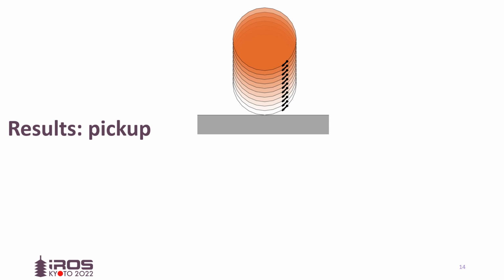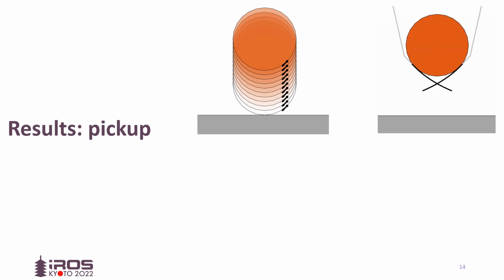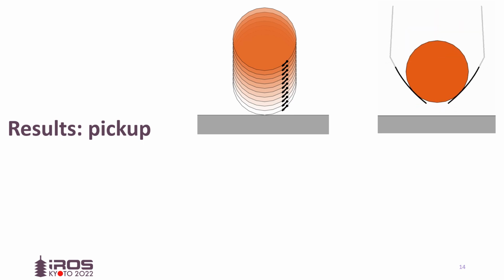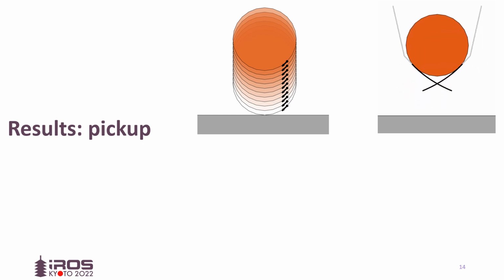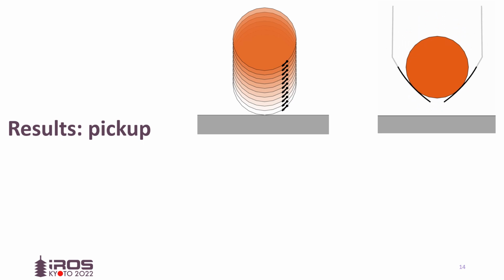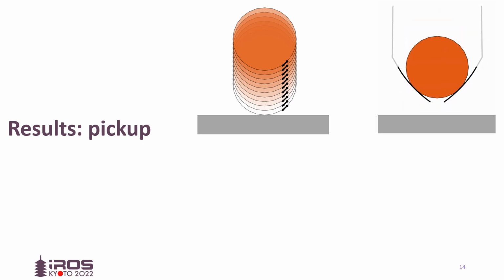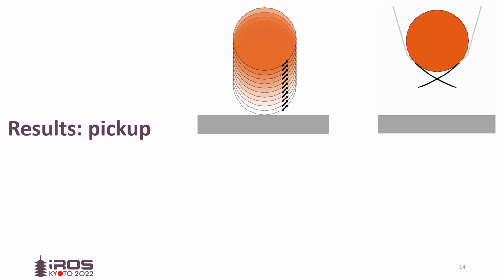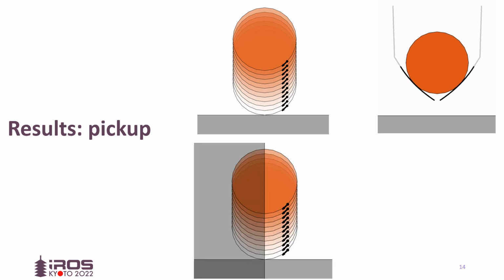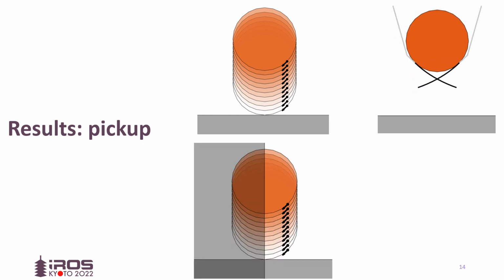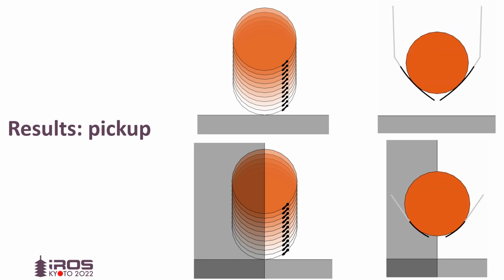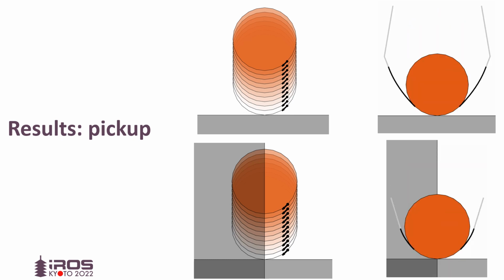We demonstrate our method on a variety of problems. Here, we design fingers to scoop a disc up from a table without translating in the vertical direction. Our nonlinear program formulation allows us to model the table as an obstacle, constraining that the fingers do not intersect it. Notice, however, that the fingers intersect each other. We can prevent this by modeling an additional obstacle while still minimizing vertical translation of the effector.